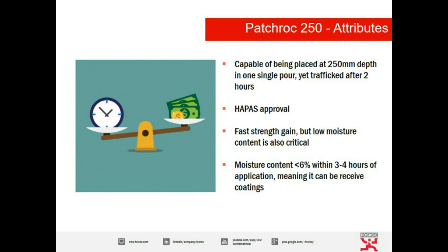In the instance of Fosroc 250, what you've actually got is a product that gets down to less than 6% moisture content in a few hours. And therefore you could, in principle, have the situation that a repair is done first thing in the morning, and by the afternoon, a waterproof coating is sprayed over the top in readiness for the asphalt. So we've all been past those roadwork scenarios where this process tends to take a long time. In the case of Fosroc 250, it can be done fairly simply and within a number of hours rather than days.